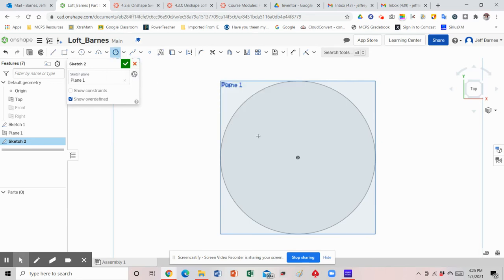And now you have some options of what types of polygons. So you can do pentagons, hexagons. We are going to create a hexagon, okay? So I'm going to go to my center point. I'm going to click once, okay? And I'm going to basically open it up to a certain size. It doesn't really matter. We're going to dimension the sizes. And I'm going to try to get my bottom edge to be horizontal. So once I click, it's already on 6. Notice if I slide, I'm just kind of dragging.